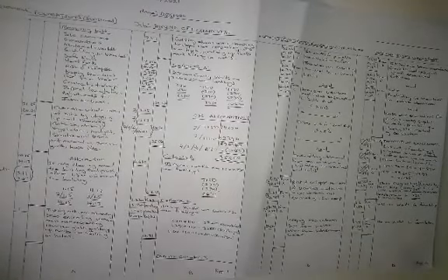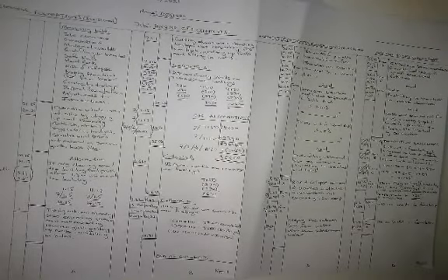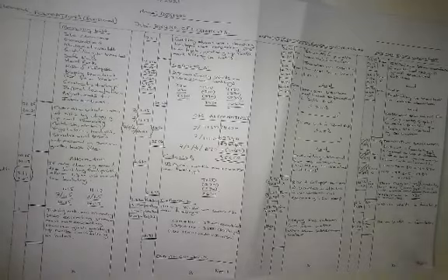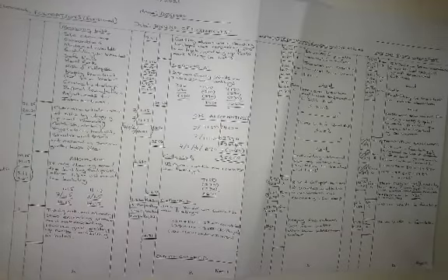First of all, when you are doing calculations and are given a drawing, you need to analyze the drawing first, check what instructions are given on it, and note any other additional information. For instance, if they say the site is already clear, then obviously you won't need to measure site clearance.